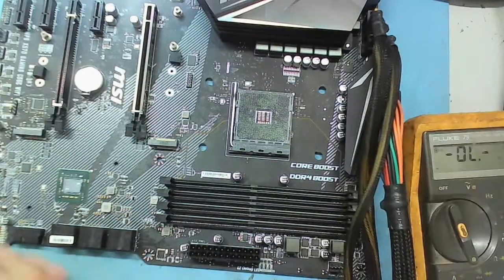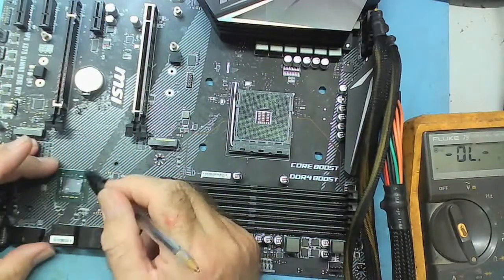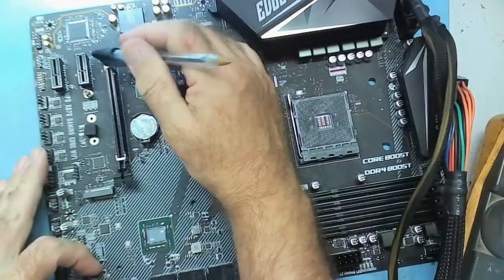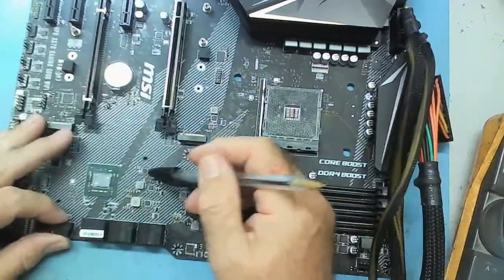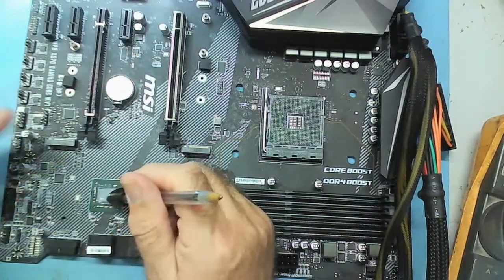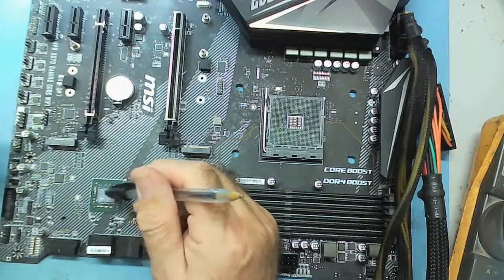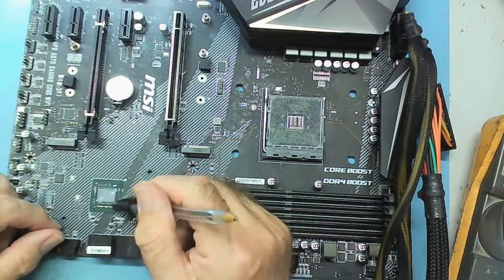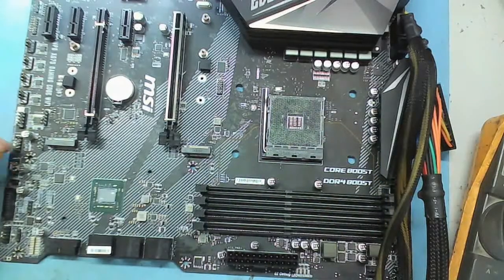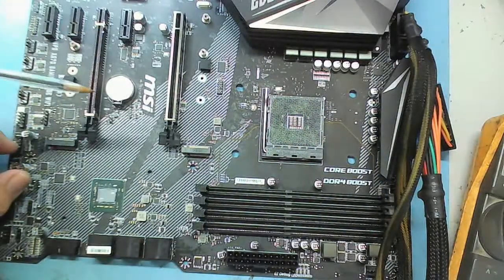We know how we found the fault, because I was measuring voltages, saying we need to have this powered up and we need to have this powered up on standby for it to switch on. It doesn't. So 3.3 volts there. I said possibly 3.3, possibly 1.8, maybe even 1.1 here, and we found less, 0.7, 0.3. I've never seen voltages below 1 volt on a working motherboard, not as I can think of, really.